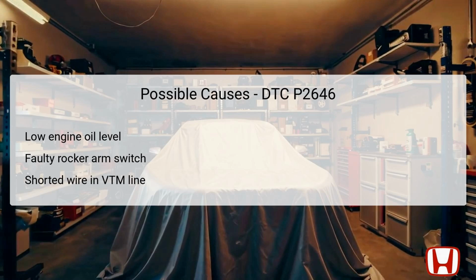Another potential cause is a shorted wire within the variable torque management, or VTM, line, impacting electrical connections and signal transmission. Each of these factors should be thoroughly evaluated in conjunction with the diagnostic test results to locate and remedy the root cause of the issue.